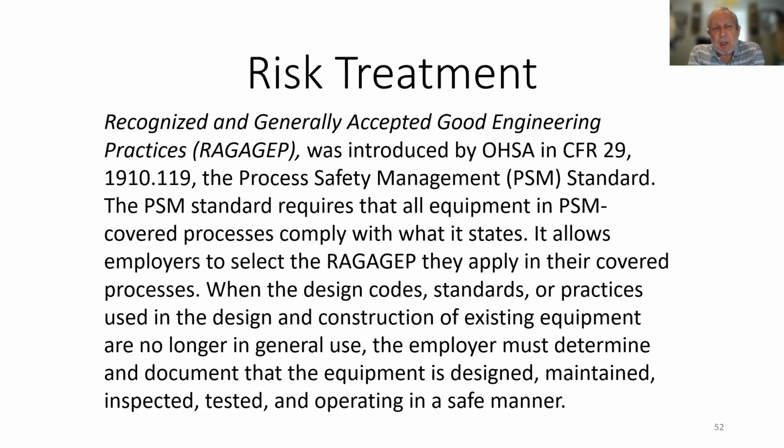Recognized and generally accepted good engineering practices, or RAGAGEP. You come across this a lot in OSHA, and particularly in process safety management. It was introduced by OSHA in 29 CFR 1910.119, which is the process safety management standard, which requires all equipment in PSM covered processes to comply with what it states. It allows employers to select the RAGAGEP they apply in their covered processes.